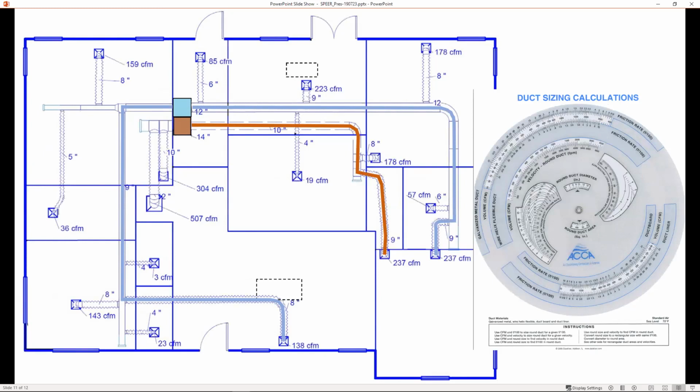Thoughts in general on, I see more contractors than not just using the diffuser as the balancing damper and not installing balancing dampers at the plenum. Yeah. Is that not a fan? Yeah, it's for airflow control. It's much better done at the trunk duct. Something is better than nothing, but a professional HVAC contractor is going to have balancing dampers and is going to shoot for this 85.